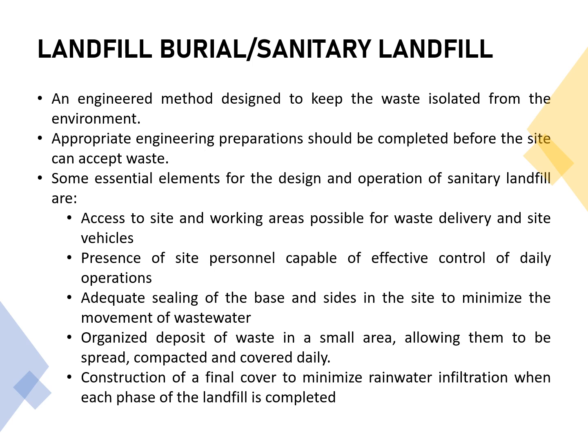So our sanitary landfills, although they are big, they are wide, and they can accommodate a lot of waste from different institutions or facilities. If there is too much waste being dumped and not properly compacted or spread, eventually the sanitary landfill will be full of waste. So there should also be people responsible to spread and compact and cover the area where the wastes are usually dumped.